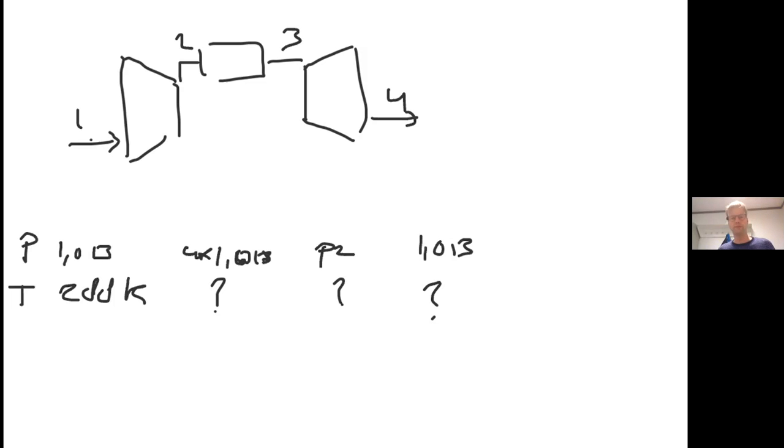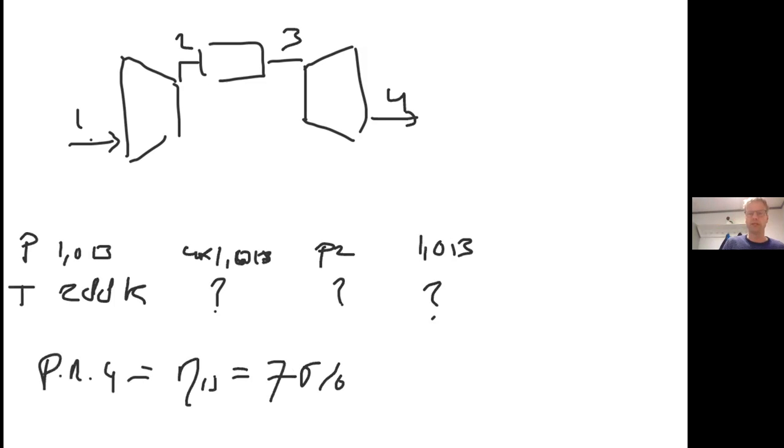That's important to know. If we look in the compressor diagram, and for example we start with the pressure ratio of 4, we see that the isentropic compressor efficiency is 75%. So we do that calculation. This is one of the cases. And we also see in the same compressor diagram that the dimensionless, reduced mass flow is 342.